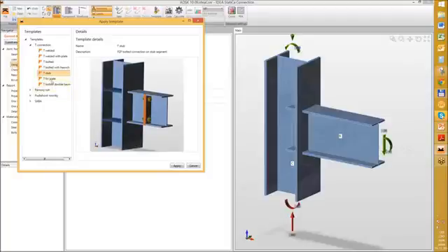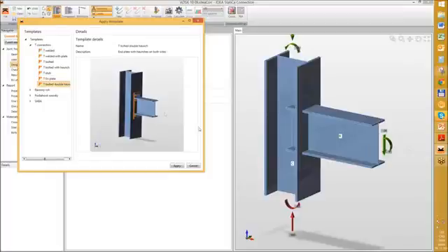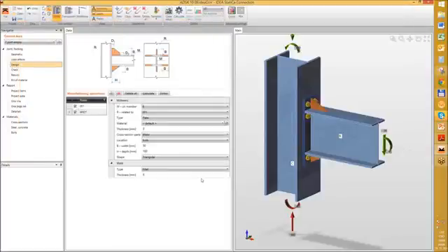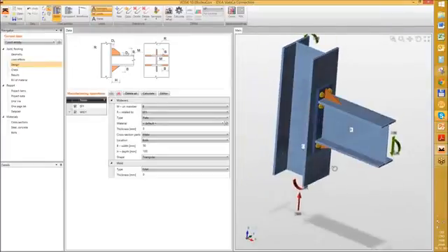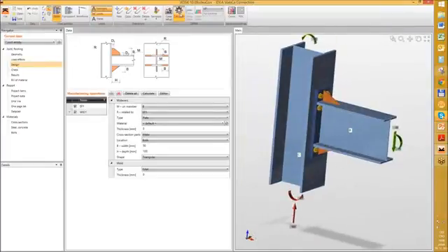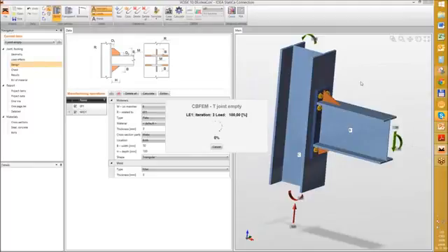It's done also very frequently. We can have also the simple connections like a fin plate, or such connection with double hinges. If you find the template which you like, you say only apply, and the connection is constructed, and we can calculate it.